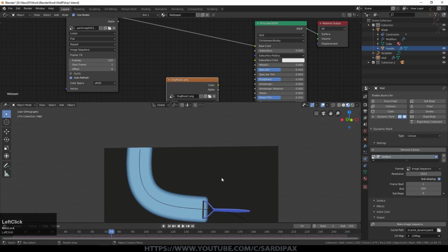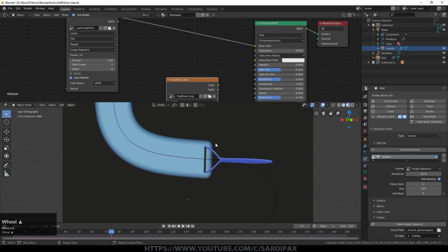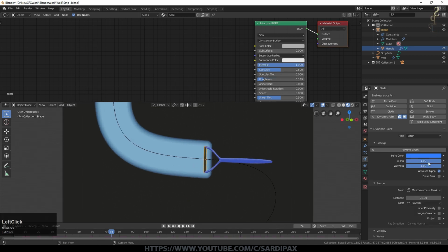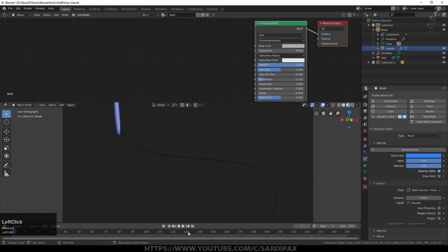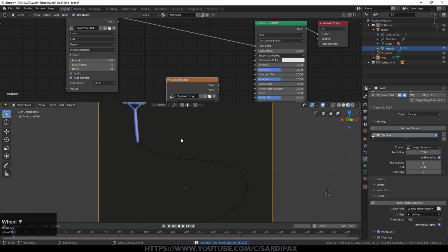properly. Now obviously for the scale of image I've got at the moment, the proximity I've got there is much too large because it's much larger than the blade itself. So I'll go back to my blade and under distance I'm going to go to 0.01 now and we'll rebake the image map. So let's have a look at that.